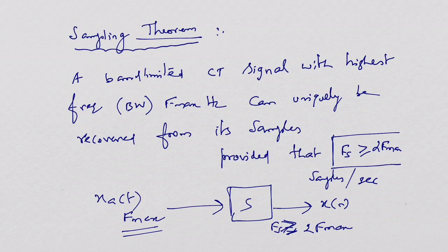What will be the difficulty of using the Nyquist rate? It produces zero sample sequences because of sampling at zero crossings. To avoid zero crossing sampling of a sine wave, we have to select fs far greater than 2 f max. F max is the maximum frequency in the analog signal. Thank you.